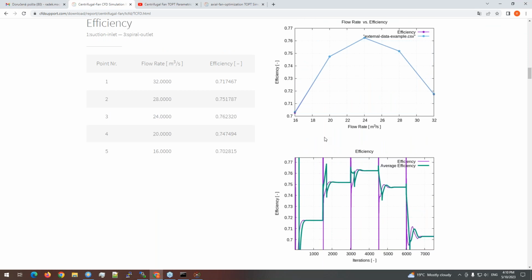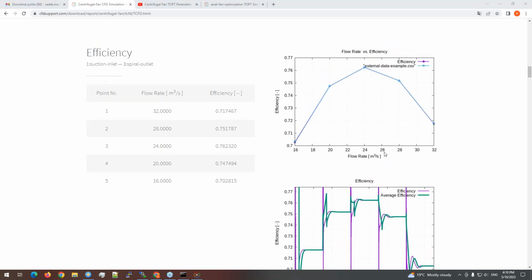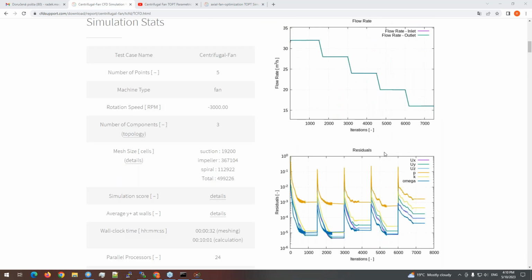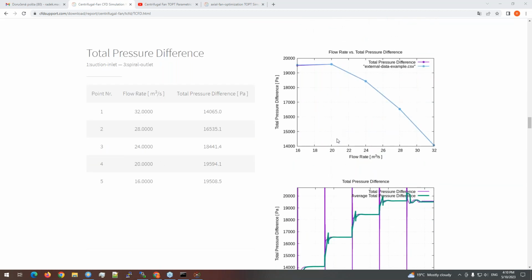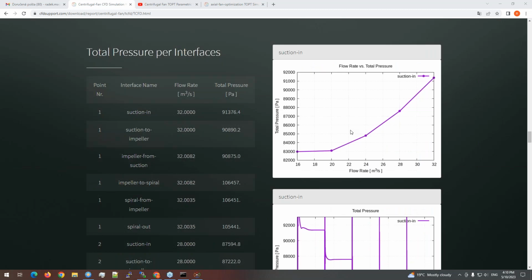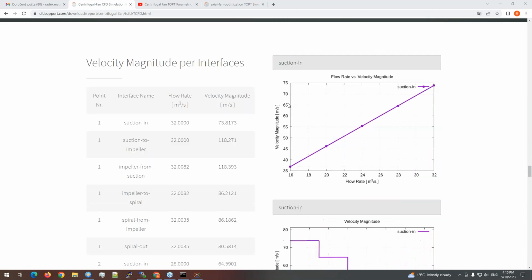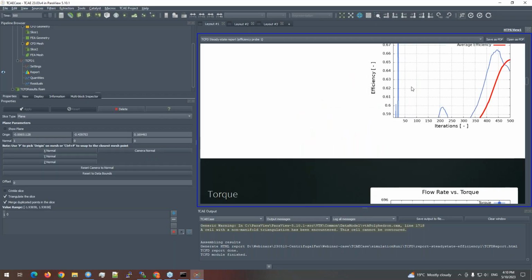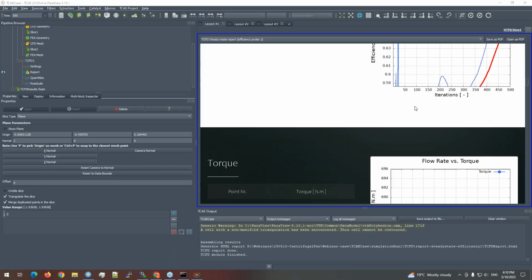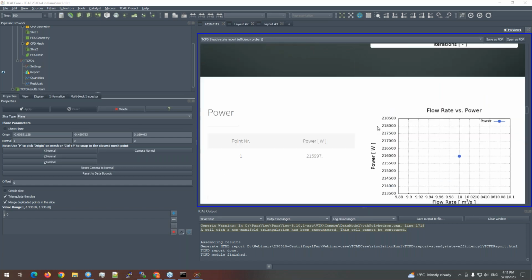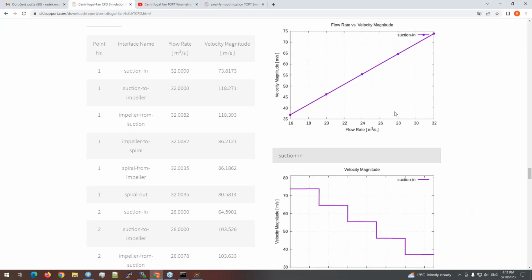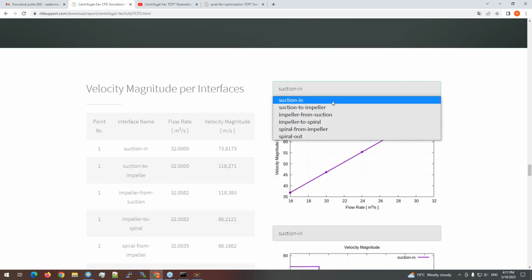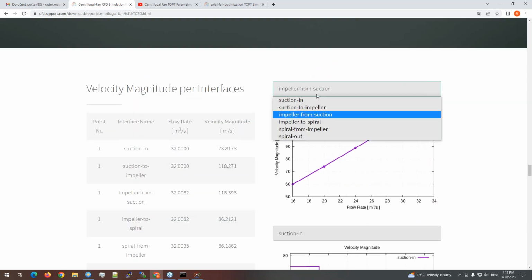There's a good, typical question from Gokul: whether it's necessary to use steady state, or whether a transient simulation would be more suitable. I'm rephrasing the question here. It's always a question whether to go to transient or stick with steady state. Normally, in standard turbomachinery, the steady state simulation is so much cheaper than transient in terms of resources and simulation time that most of the users still use steady state.